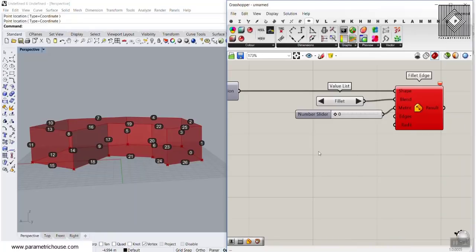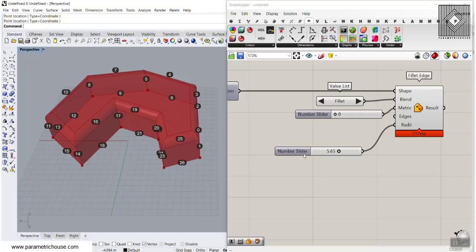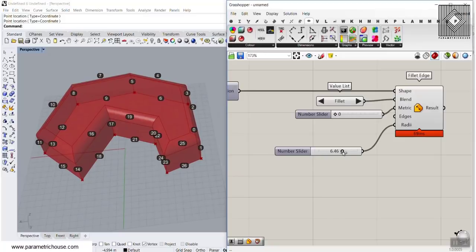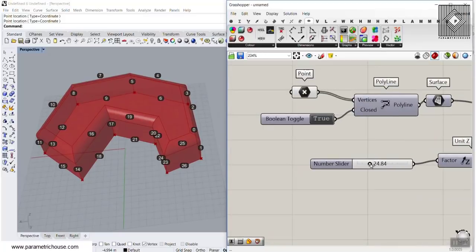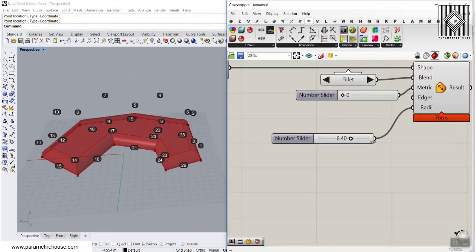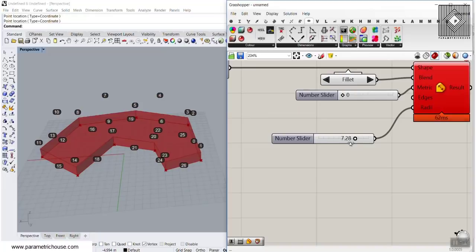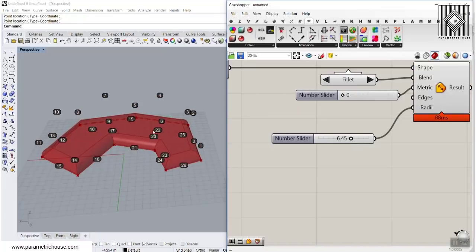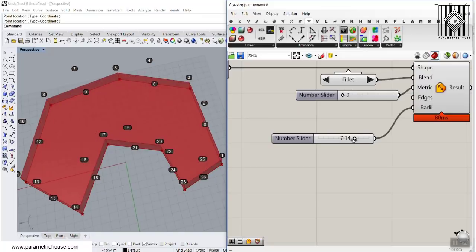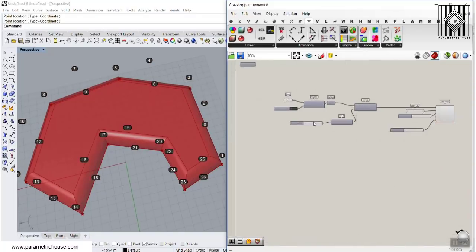Okay, and then give this a radius. So let's just do this. And perhaps we have to change this number to get the results. You can see that I am filleting all of the top edges I want. So we can change that and maybe just decrease the Z direction extrusion. So we'll just have a simple fillet. And you can see that you can't just increase that because there's a place where those fillets will fail. So remember, you have to play with those numbers.